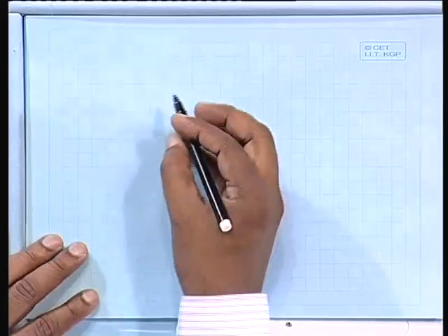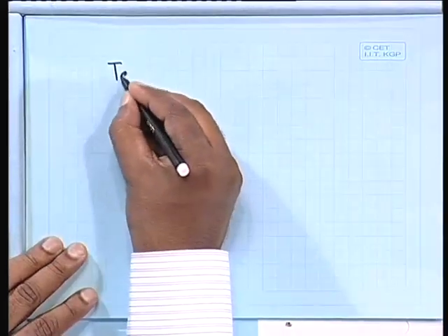Please note that it is not Ly square and Lx square. Generally you do that mistake, but please note that in both the cases we are taking q L square x, and beta x and beta y are coefficients, and these coefficients you need not calculate again. What you have to do, those coefficients you will get in table